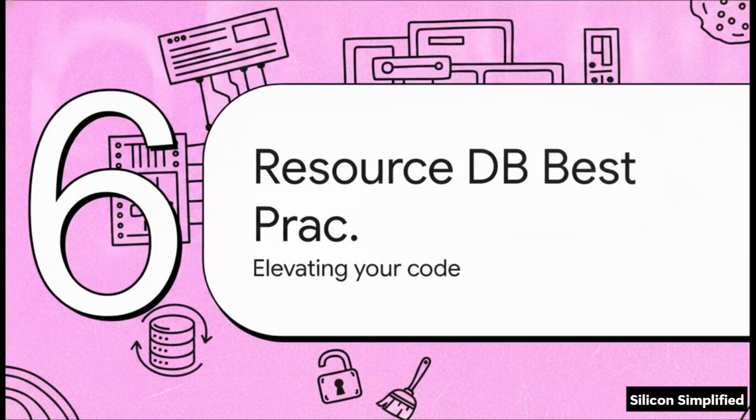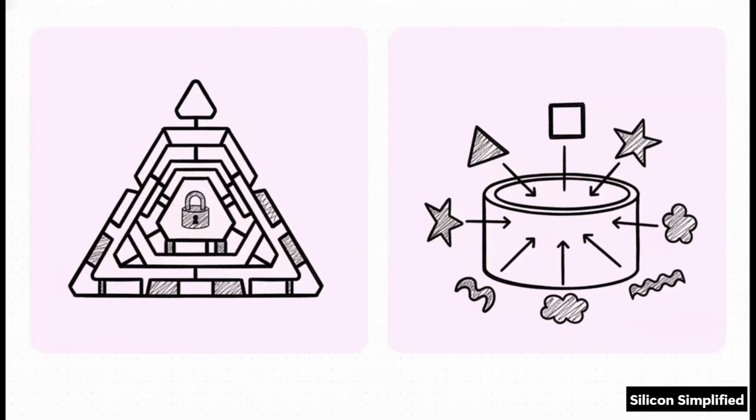Finally, Section 6, Best Practices Resource Database. Now that we've built a complete, working UVM environment, I want to wrap up this masterclass with an industry best practice that will truly elevate your verification skills and seriously clean up your code. Look, sharing configuration data, like virtual interface handles or test parameters, across a deeply nested test bench can be a massive headache. While honestly 90% of engineers out there just use UVM_config_db out of habit, verification experts often point out that transitioning to UVM_resource_db is vastly superior.